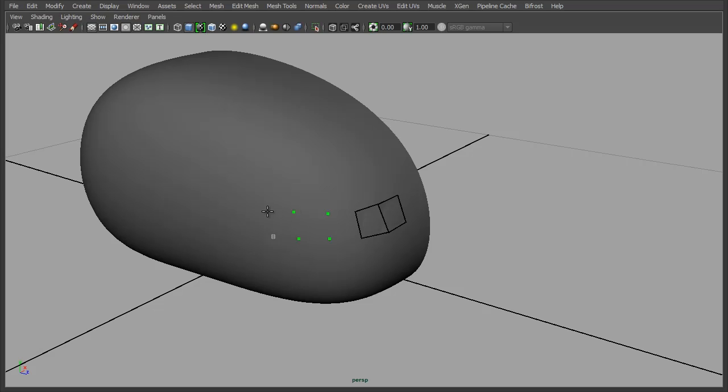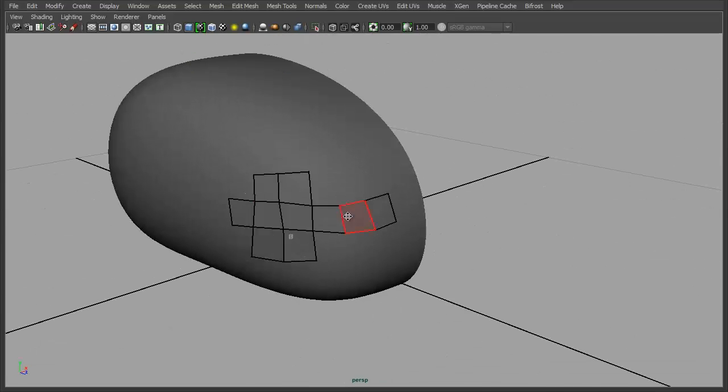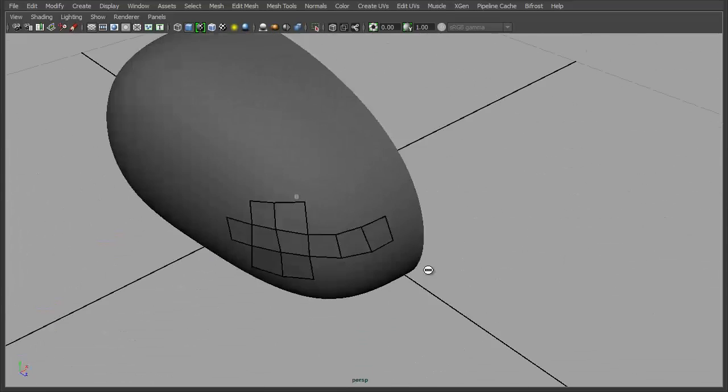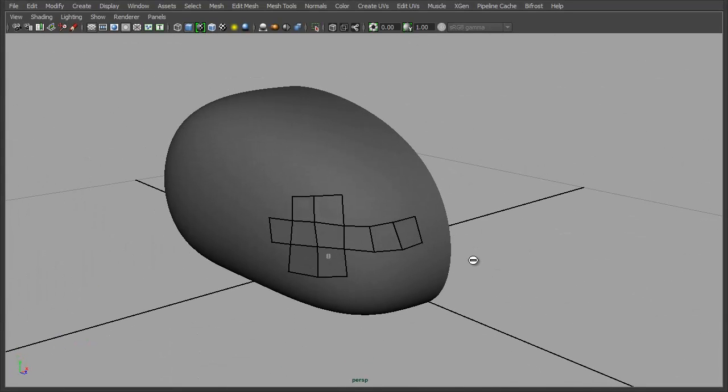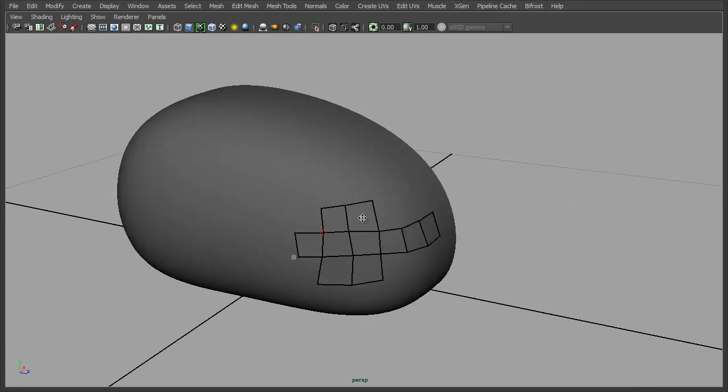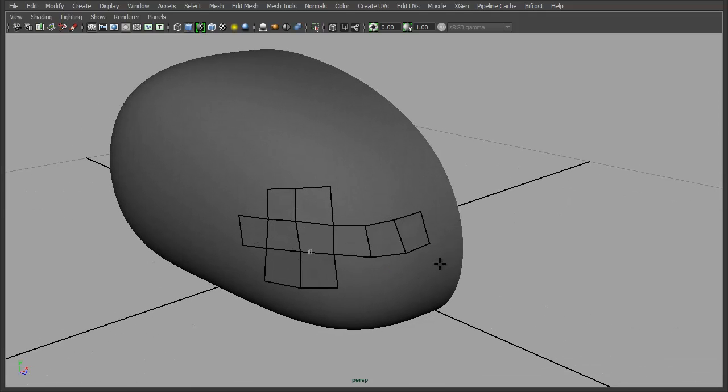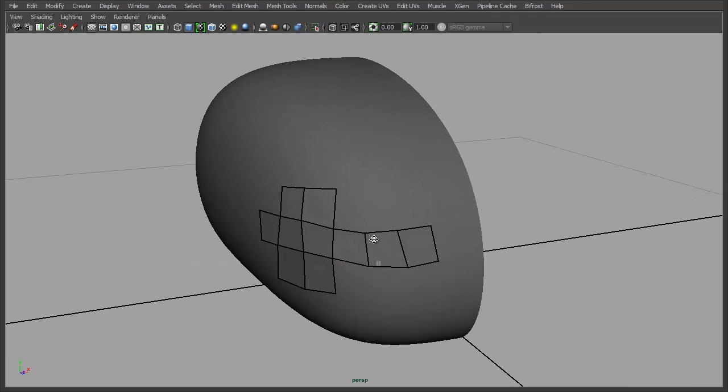And we don't need to just do it on each one in turn. We could come round like this and just add our points in, like so. And then go over with Shift held down. And you see there, you can decide how you want your polygons to flow, depending on where you place them. So as you can see there, we've got the polygon strips added in, and they're following the surface of this model. And as you can imagine, if you'd sculpted a high detailed model, brought it into Maya, you could easily use this to create a nicer, cleaner, low resolution version.